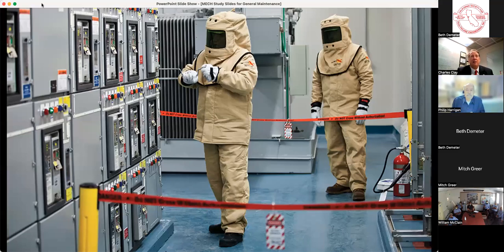This is a couple folks that are doing some electrical switchgear work, and if you notice, the protective equipment they have there is much greater than what you may normally see out there. But they're actually what we call racking a breaker. They're taking a breaker out, and he's cranking it right there. They have their safety distance out. They got their arc flash suits on.